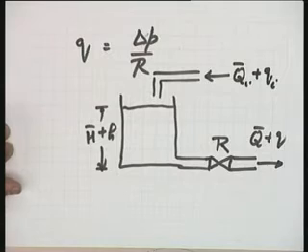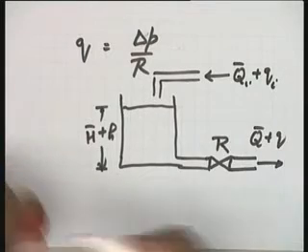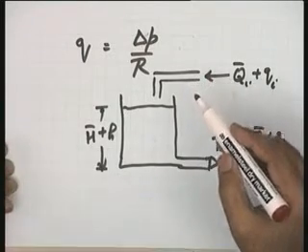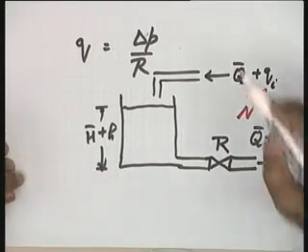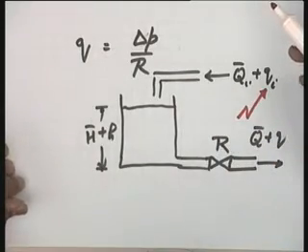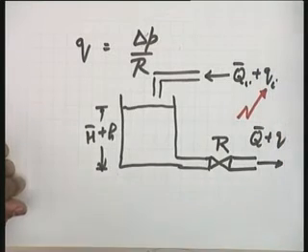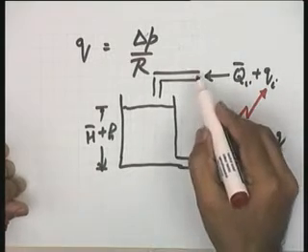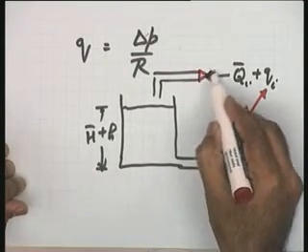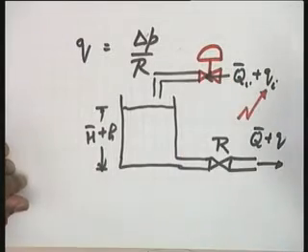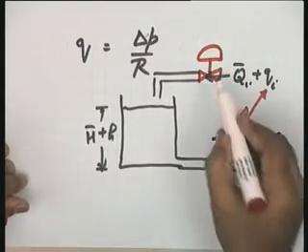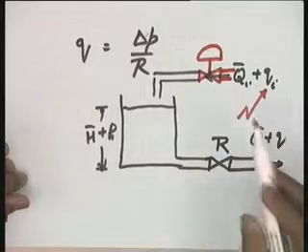Now, since we understand the restriction, I can put a restricted flow at the input side also. After all, as you have said, your Q I is a manipulated variable. It is the variable you will control. How will you exert your control? You are going to exert your control by controlling the opening of a valve. So, I think it will be appropriate if I put a suitable valve over here, but with a control available in your hand. So, in this particular case, this becomes the situation.